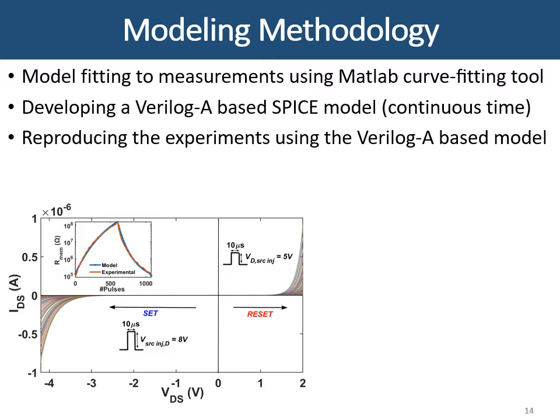We developed a Verilog-A model based on the fitted parameters and used it for circuit design and simulations of different applications, which reproduced the basic experiments with high fitting accuracy, above 98%, as shown in the reproduced hysteresis figure of the Y-flash device, which is a typical characteristic of memristive devices.